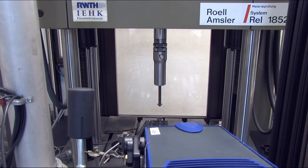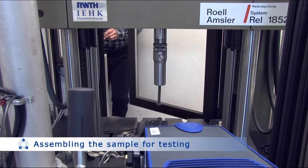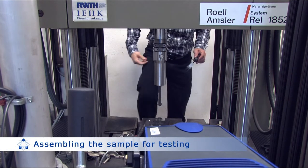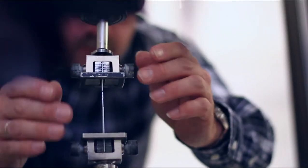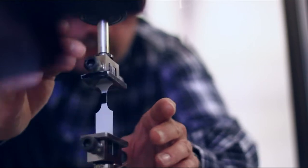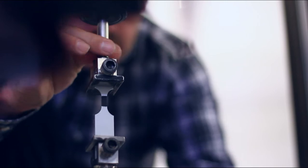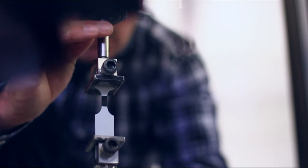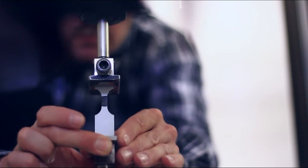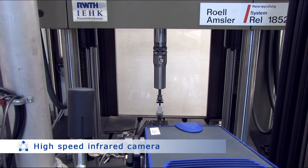The high strain rate tests are performed on the servo-hydraulic high strain rate testing machine according to SFB 1230. The tests are performed to characterize the material's behavior under crash conditions, especially for the automotive industry. In the context of material testing, the rise in temperature affects the results. Hence, at the Institute of Ferrous Metallurgy, the sample warming during testing is measured with a high-speed thermographic camera.